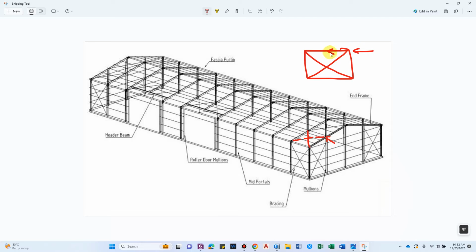And this strut, now if we see here, this is a purlin, and it is subjected to a wind load as well. And due to the wind load, considering this as a simply supported connection, it has a moment, and at the same time, due to the lateral wind load, it is also subjected to an axial force. Now we have to consider the combined action. So this purlin cannot be designed just for bending moment, it has to be considered for the axial force as well.